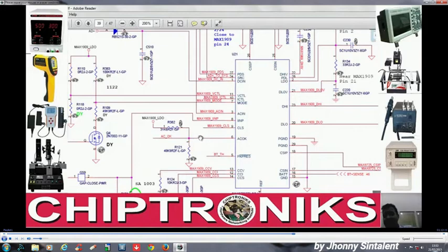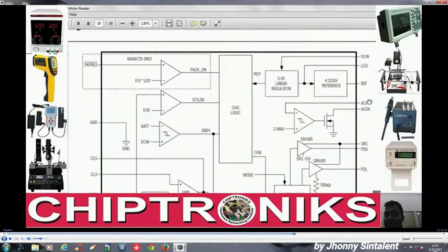And if the adapter is not present, then what would be the scenario? If the adapter is not present, AC in is not present, then this comparator input is 0, so it will give you a high value. That means this MOSFET will turn on and this switch will close, and this AC OK would be 0. So if AC OK is high, like 3.3 volt, that indicates the presence of the AC adapter. It's a very good comparator inside this charger IC. Okay, we'll understand each thing slowly. Yeah, let's go to page number 13.